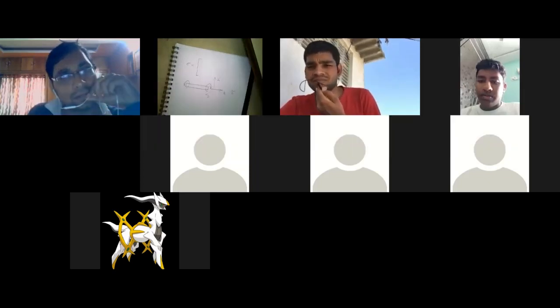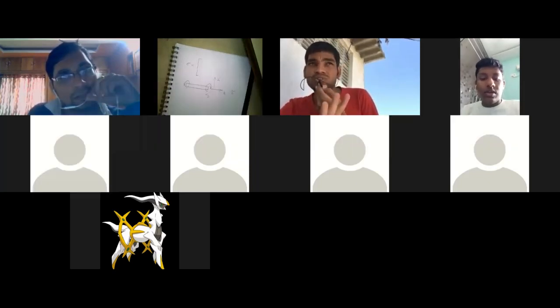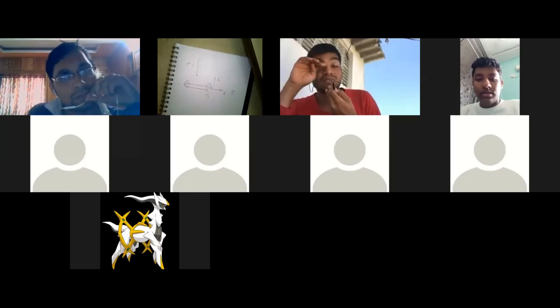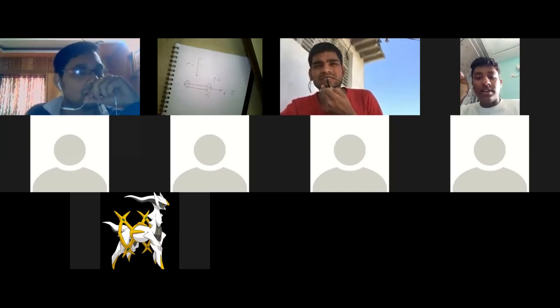About 1 we are rotating. Sir, about 1 it is rotating, so on what face will you see this stress? Tau 2 3 on the face. No, the face, because what is the normal direction of the face? Sir, 1. So 1 is the normal to the face on which the shear stress appears.